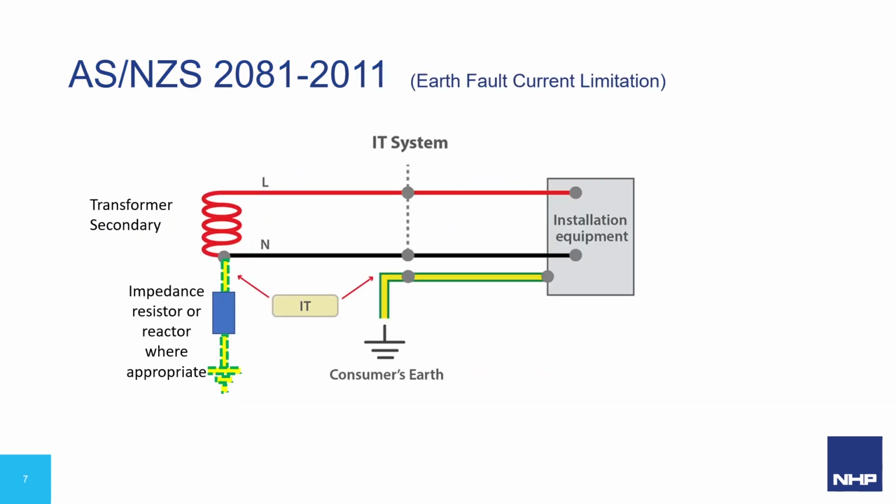The standard AS/NZS 2081 nominates the performance and design for electrical protection devices used in mines and quarries. In association with AS/NZS 4871, it provides guidance on techniques for earth leakage and earth fault detection and mitigation, as well as prevention of danger caused by rise in touch voltage potentials on machinery used within the system.